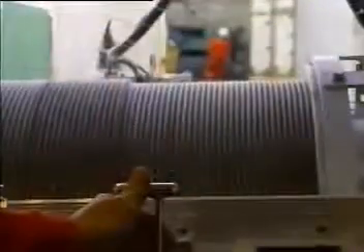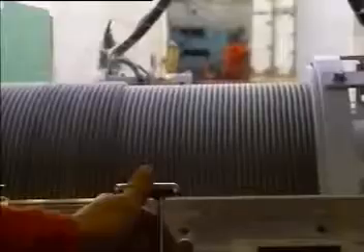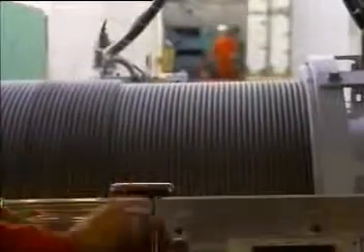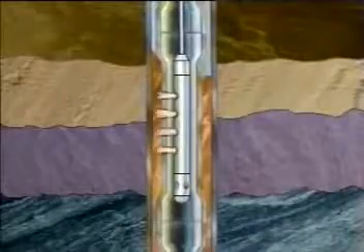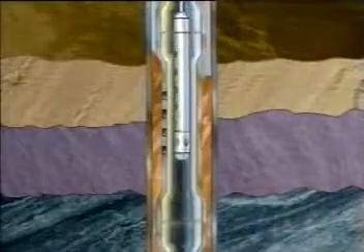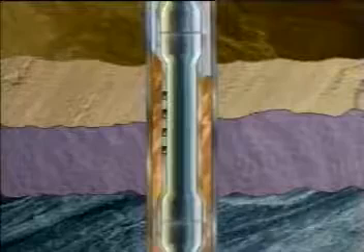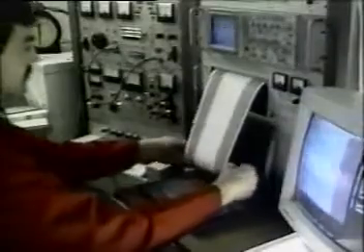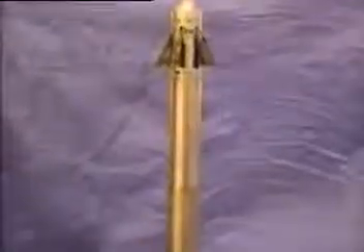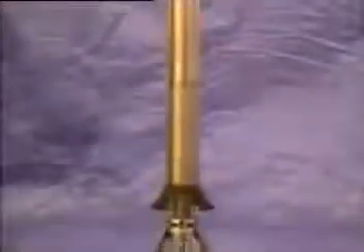In open-hole operations, special wireline tools are used to perforate multiple shots per foot in a string of stuck pipe. Perforations are sometimes necessary to establish circulation to the annulus, or spot lubricating fluid to help free the stuck pipe. Other specialized wireline tools are employed by Weatherford operators to aid in the removal of casing, drill pipe, or tubing. Wireline caliper tools are used to measure the inside diameter of downhole pipe.